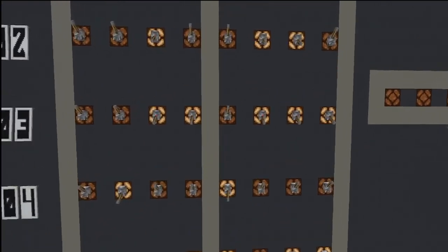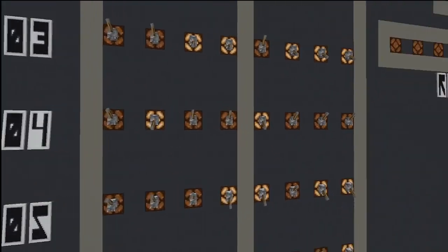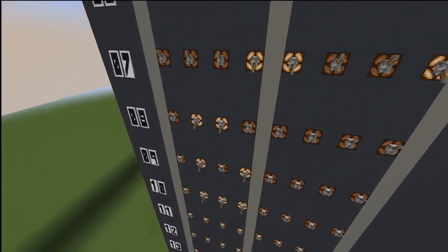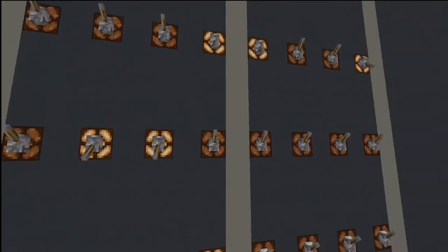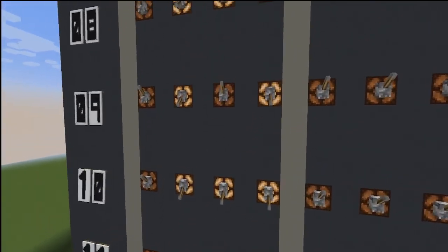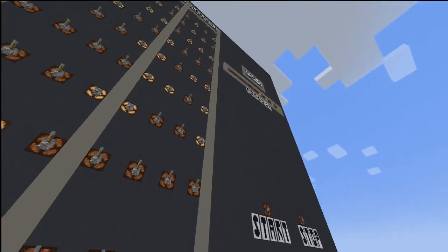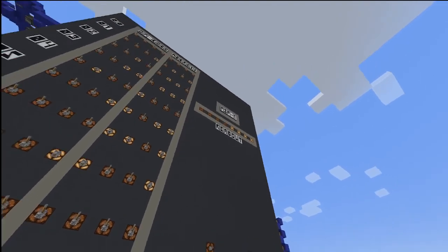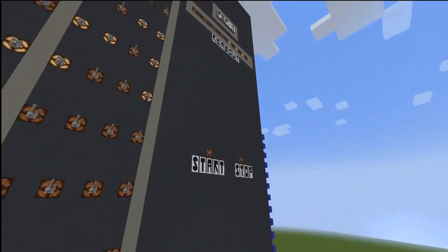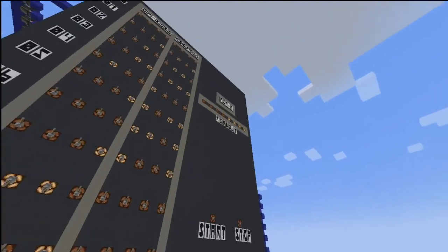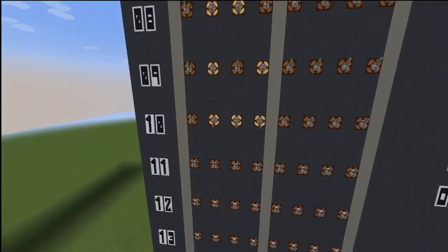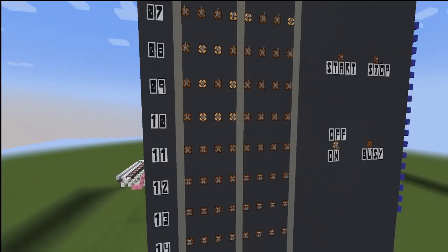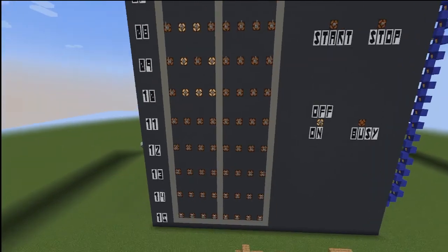And then after that, I have a jump, and so it's going to jump to line 8, which is all the way down here. And then I just have a no operation, so nothing's going to happen. And then I have an output, so the out command is just going to update the A register and copy it over to the C register, which is going to show the output, which after it does the addition and subtraction, the output should be 15. And then it's going to halt. So it's going to turn off the clock and turn off the busy light, and that'll be the entire program.